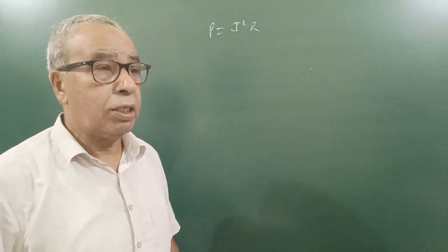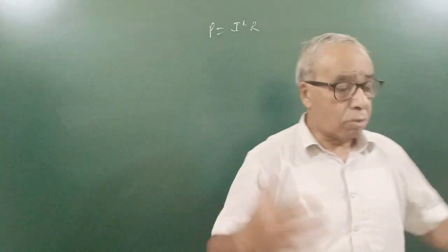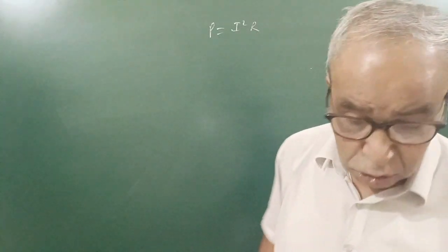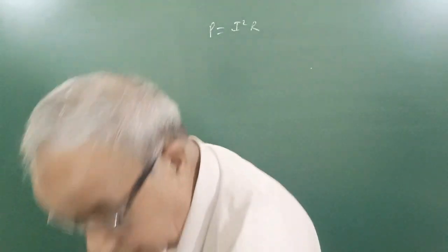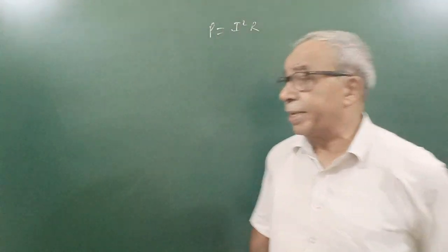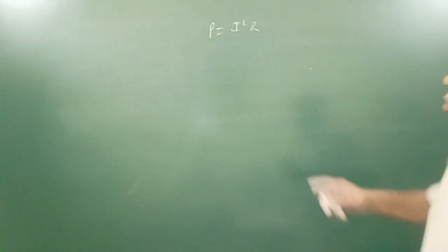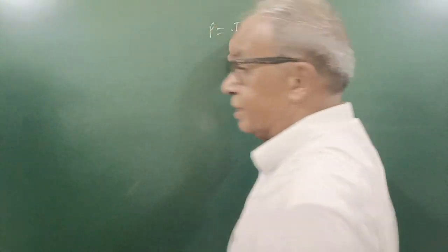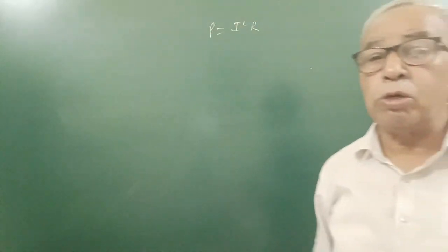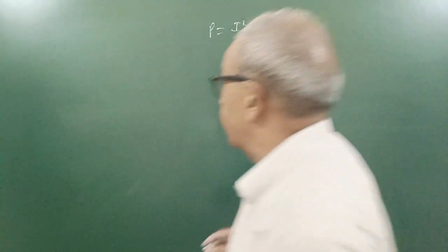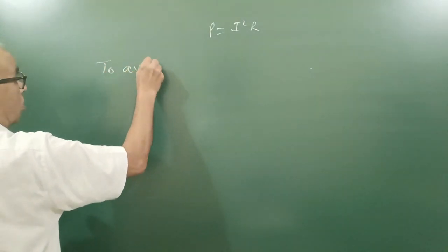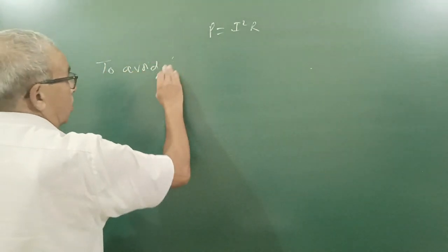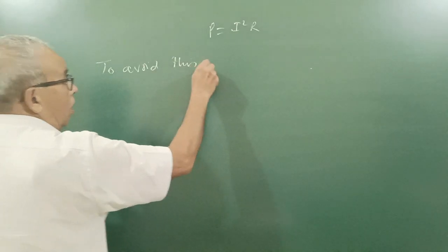Thick wires are costly, become heavy, and so we need strong pillars to support the load, and hence the line installation will be costly. So what to do? I square is the bigger factor because heat is proportional to square. So we reduce current to avoid this line loss.